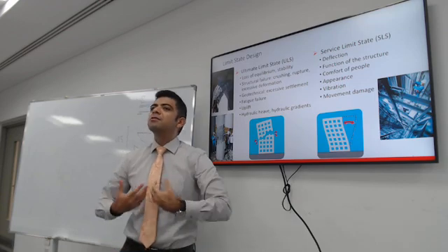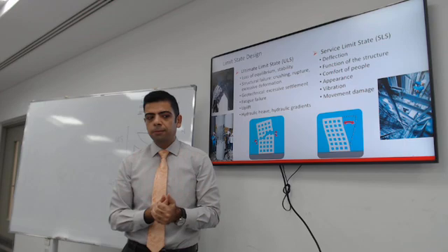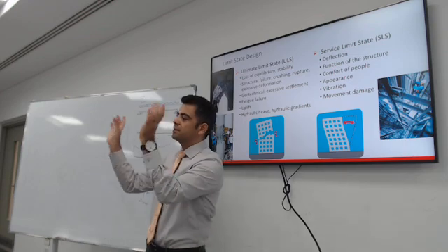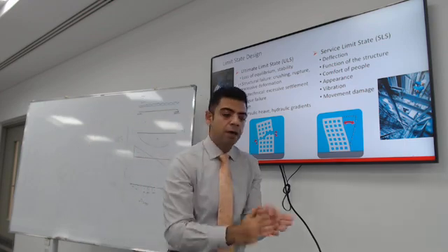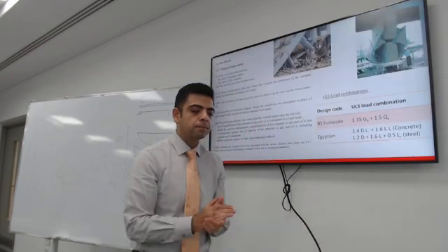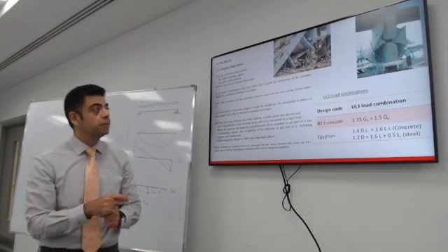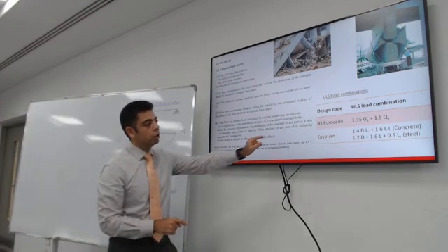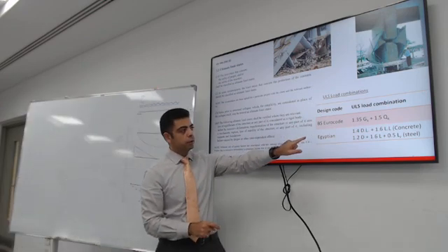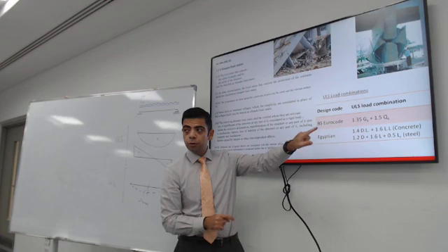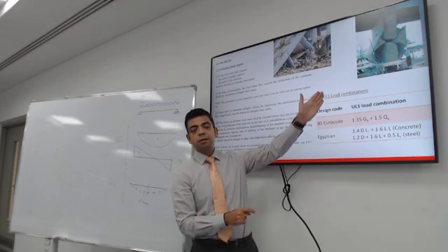It has to do with the serviceability of the structure. So these are the 2 limit states that we will design for, and they have different load combinations. Each code, each standard will tell you the load combinations you should use for each case of loading.